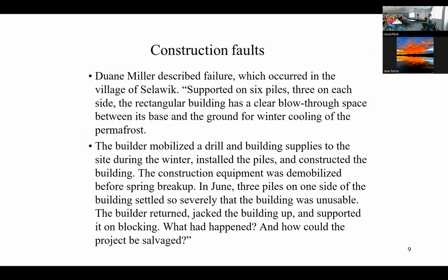In the spring, the slurry on the top started to flow, but there wasn't support slurry at bigger depths, and the building started to settle just in the first spring. And it was a big effort to fix it. No equipment on the site, no way to drill new holes and put in new piles. And they just sawed slurry in the hole, compacted it and added new. This is a small example of a construction fault.